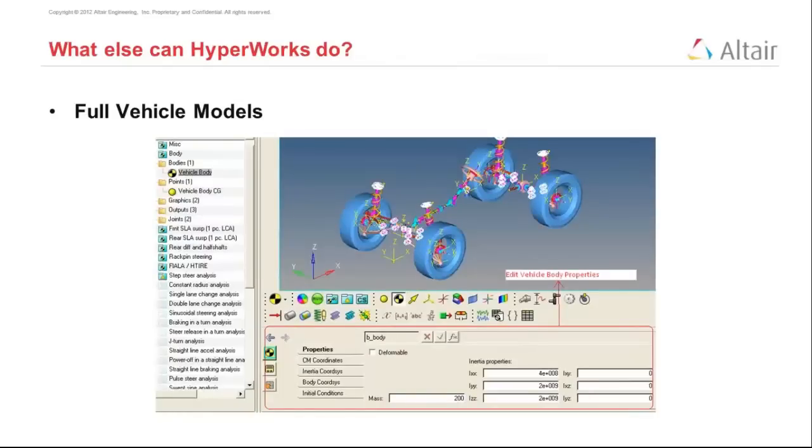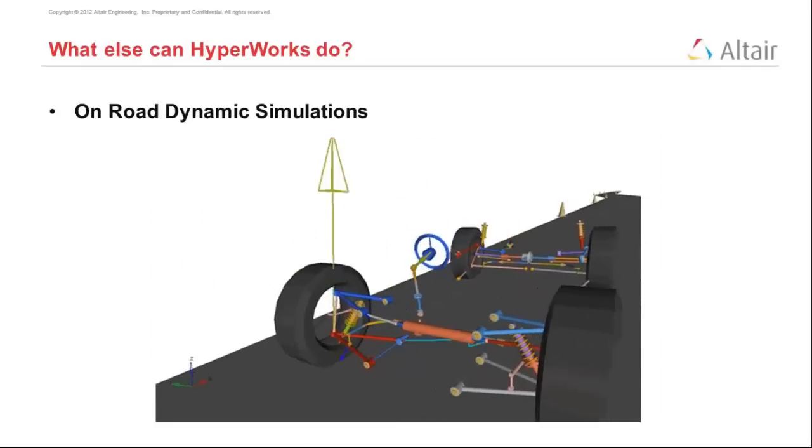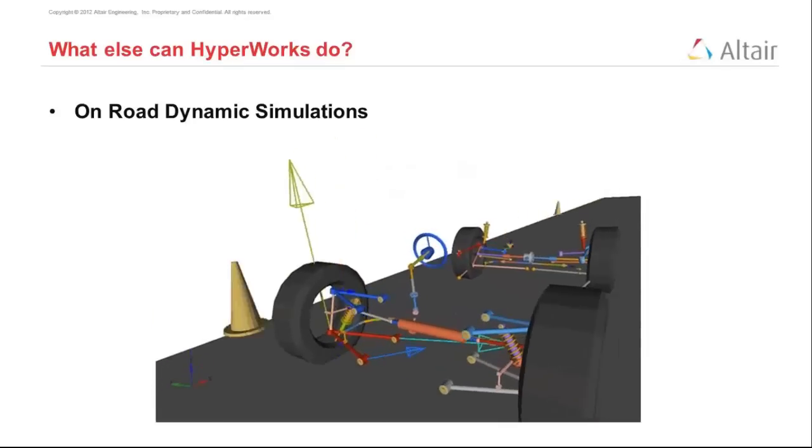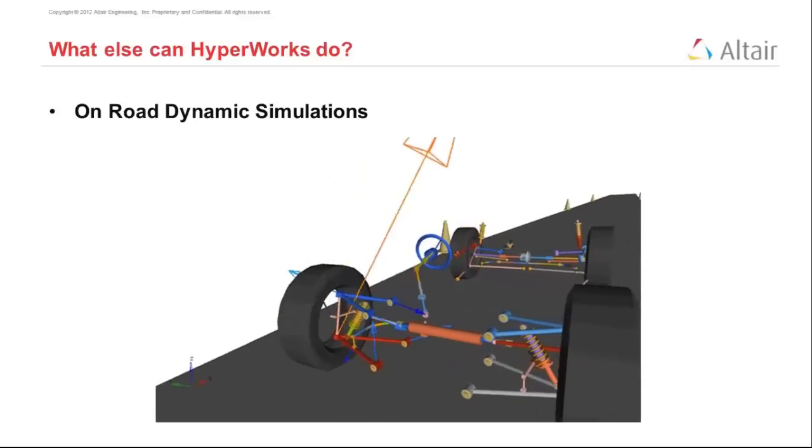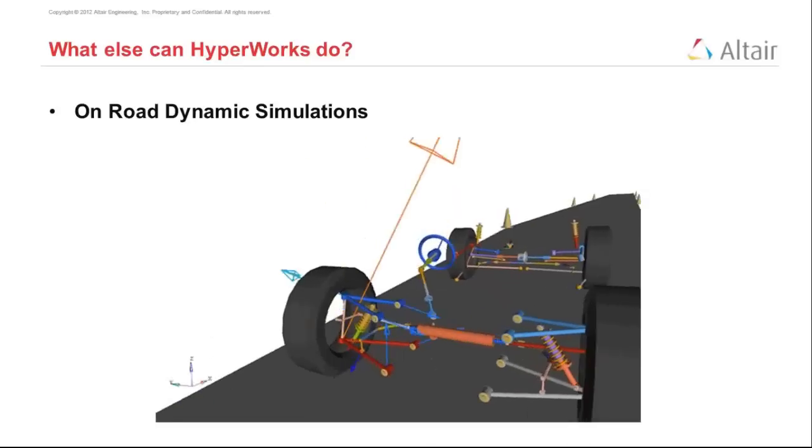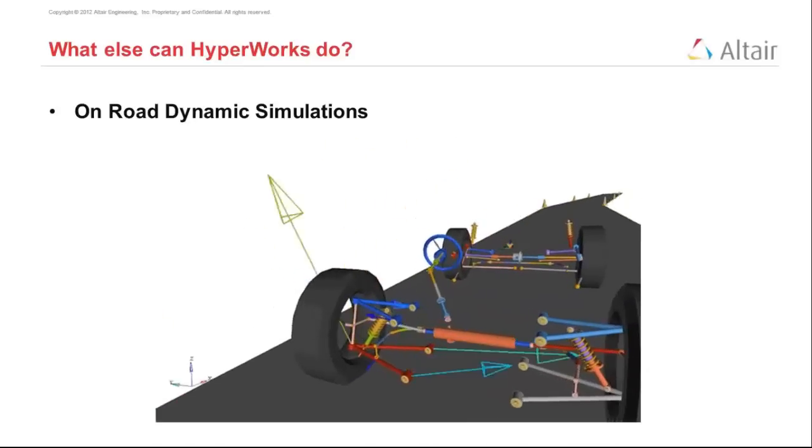We also have the capability of doing full vehicle models, which basically means you design the front half and the rear half, put them together, and then run the vehicle in simulation through different analyses. This is not going to be covered right now, but there are a few videos available which explain how to do this. The help or tutorial document available in the zip file also explains this procedure. After you have assembled both the front and rear, you can run this kind of simulation where you can see the car run beforehand. But I would recommend that you spend most of your time doing the suspension iterations and understanding the effects of camber, toe, caster, scrub radius, and the other things on the handling of your vehicle, like we went through the camber example right now.